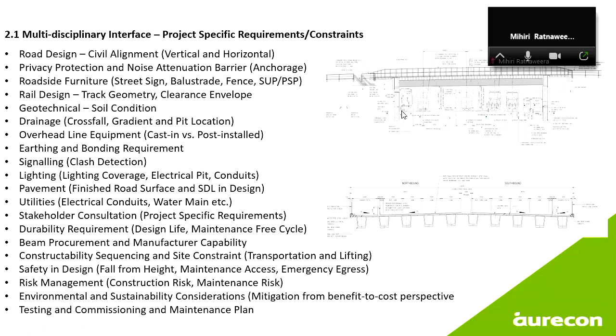As you can see, we have a minimum horizontal clearance envelope and a vertical clearance envelope that we have to design to. We have a rolled-over rail profile on the top, and then we have screens to prevent people throwing rocks onto the rail track or trying to jump off the bridge. There are a lot of aspects to it, and this is a typical cross-section showing how the Super T bridge looks across the transverse direction.